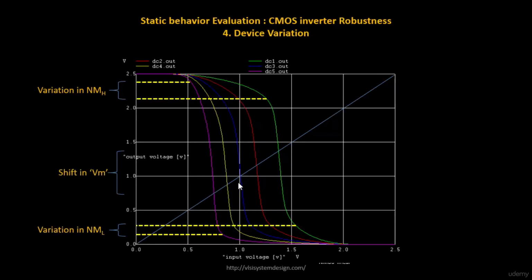It's a metastable state. But the good news is that even though you vary your CMOS inverter to the extreme cases, the variation in the noise margin is low compared to if it had been in this area. The variation in the noise margin is from this point to this point, about 2.1 to 2.4, so only 300 millivolts. Over here it's even less, about 0.2 to 0.3, let's say about 100 millivolts variation in the noise margin, but it's not huge. It's still under the acceptable range.